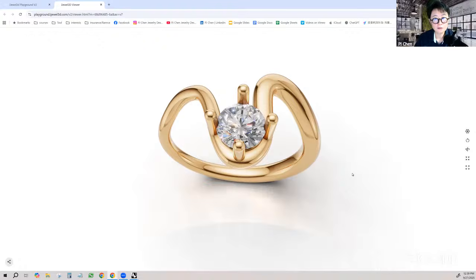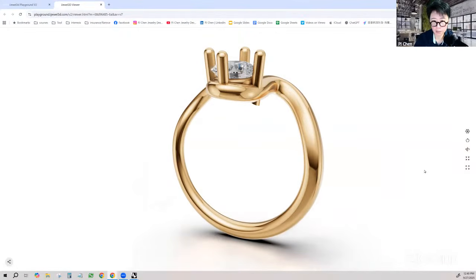A lot of the time, if the texture is like a scratch or something, you don't want to make that into your model. It will be too deep, and after you polish, it's not going to be seen, right? So that's why we need rendering, then we can assign the scratch material. But if you like a hammer mark, where you physically have a dip in it, then yes, you need to create the texture in your model.